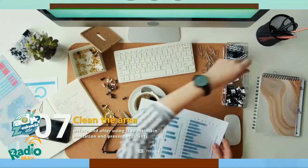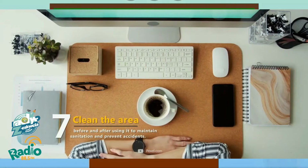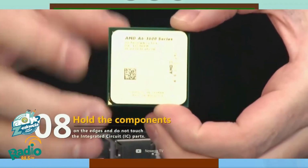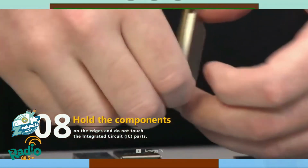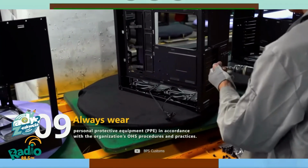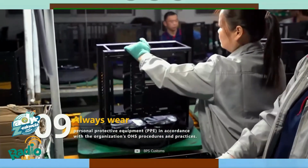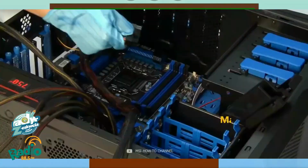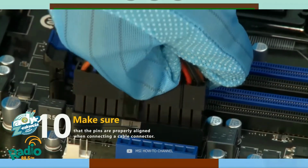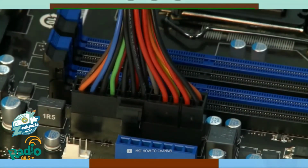Number 7. Clean the area before and after using it to maintain sanitation and prevent accidents. Remember, prevention is the best cure. Number 8. Hold the components on the edges and do not touch the integrated circuit parts. Number 9. Always wear your personal protective equipment in accordance with the organization's OHS procedures and policies. Number 10. Make sure that the pins are properly aligned when connecting a cable connector. Some pins can be bent easily and can be hard to fix.